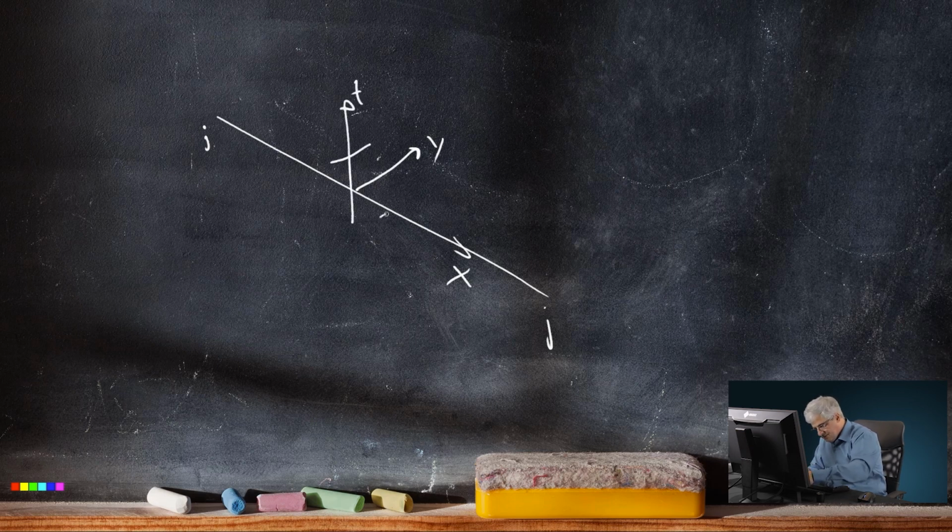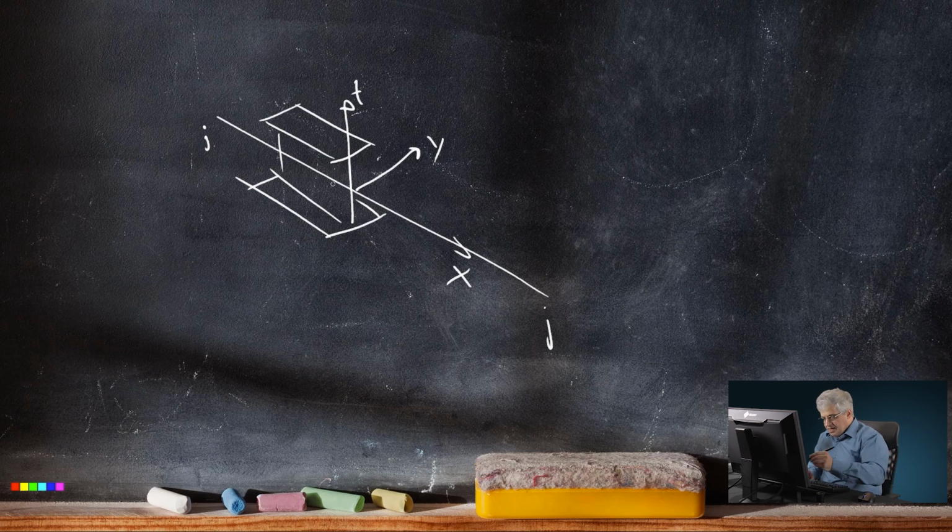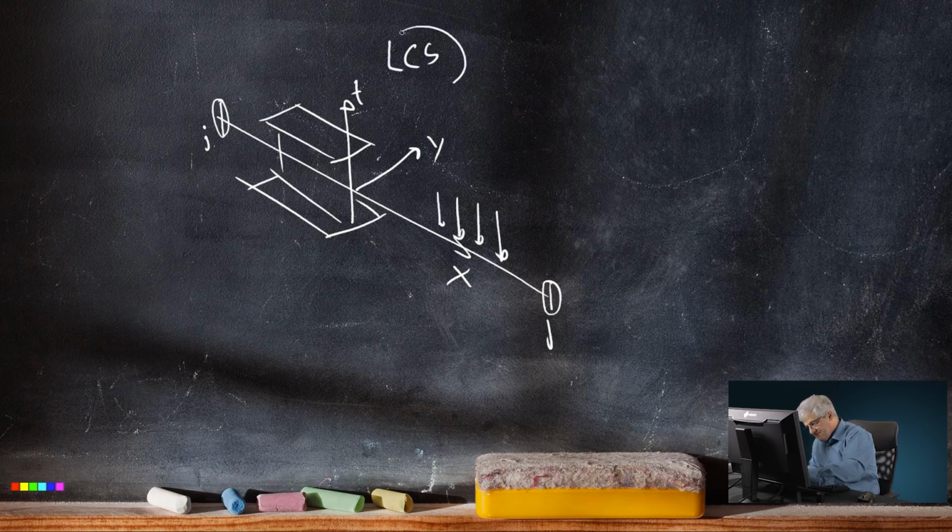This is the drawing of my member. On this local coordinate system is connected the cross-section. On the local coordinate system, there are connected also the hinges. So I can draw some hinge, some vertical hinge. And also loads are connected to this local coordinate system.